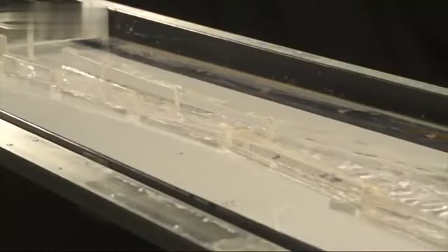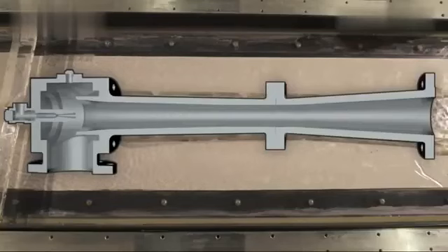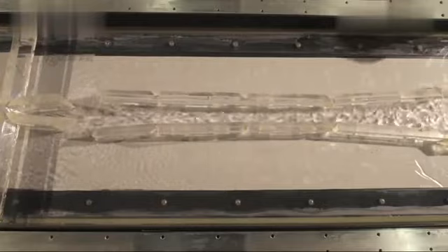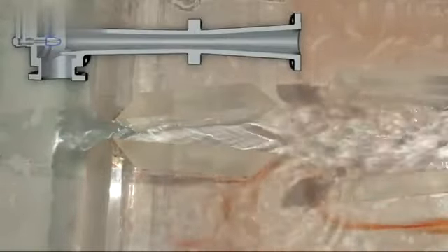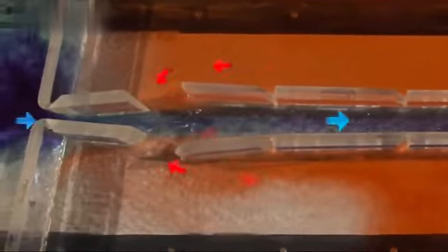To further expand on the principles of operation, here we have a 2-dimensional hydraulic simulation of the flow through an ejector, which can be visualized on what we refer to as a wavetable. The height of the water in the wavetable is analogous to the pressure in an ejector. The motive nozzle expands the high-pressure motive fluid down to a pressure lower than the designed suction pressure. As the high-velocity motive flow leaves the nozzle, it comes in contact with the suction fluid and begins to mix with it, entraining it as you can see here. The pressure will slightly increase through this section, causing the water level on the wavetable to rise.